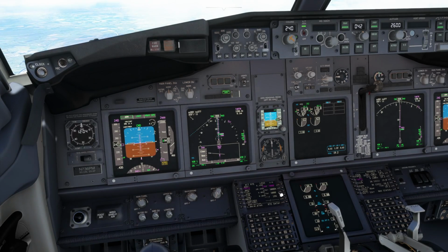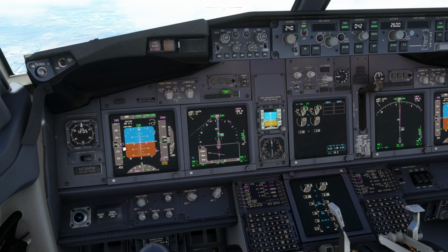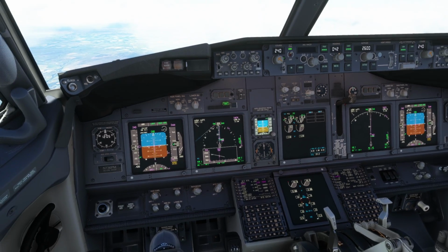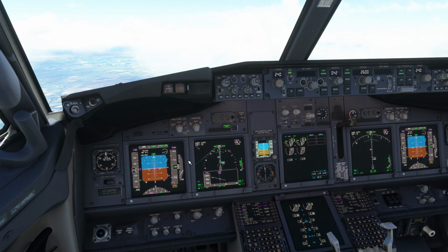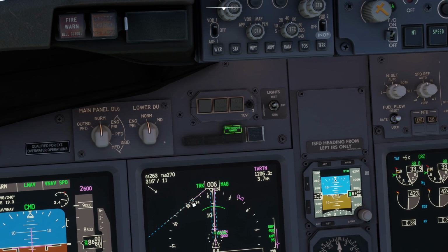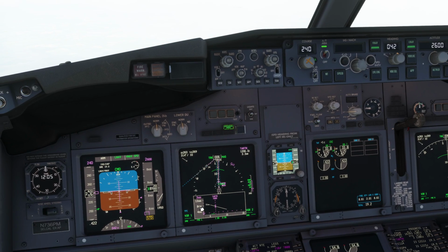So you'll see the target airspeed keep changing as we make these different decelerations. So we're at 240 at the moment. We should be going for 230 at Tartan. So we'll help it. We'll go and stick the spoilers out now, so when it comes to do it, it will be able to do it easily. So on the map you can now see there's the airfield. There's our turn out towards the approach, and then we turn into the approach.